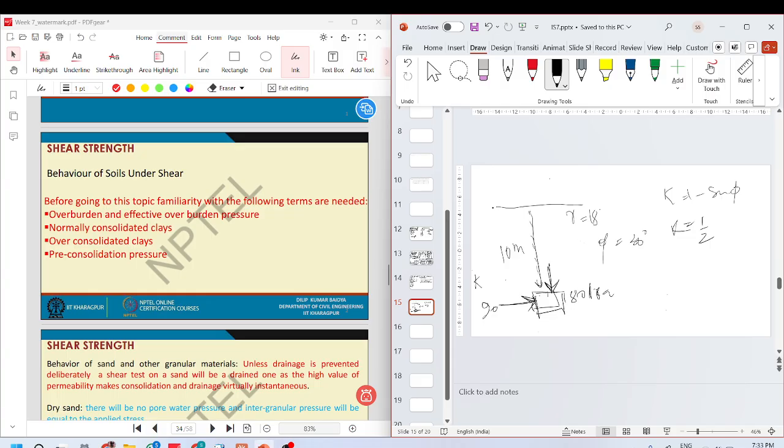Given that this was the state you find the soil in, and the soil has been depositing only, you will know the pre-consolidation pressure. But now if, due to some action, like an excavation, or erosion or something, some of the overburden over this soil was removed.